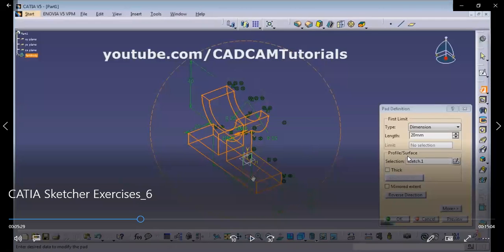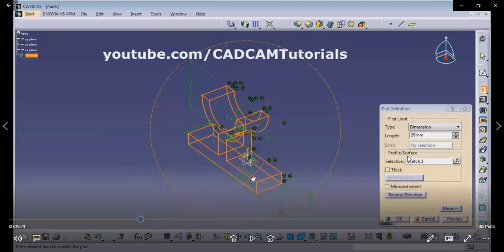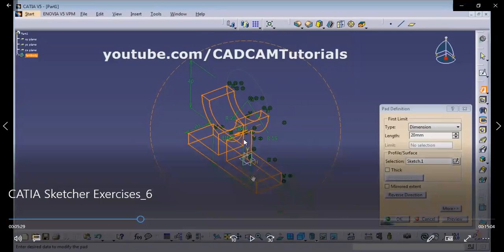Okay, so for creating that rib, for convenience, we are using this middle plane. Otherwise we could have dragged it in one direction only, right? The total pad could have been taken in one direction, but just so we have that rib feature in the middle, we can use that same plane, right? Your middle plane, the one where we created the sketch. So that we can use it if we use this pad on both sides.